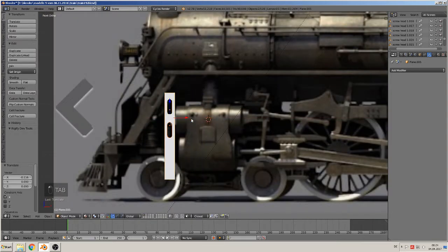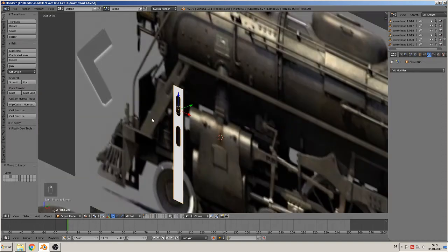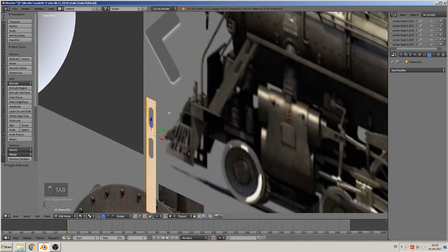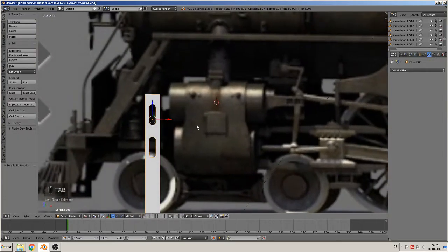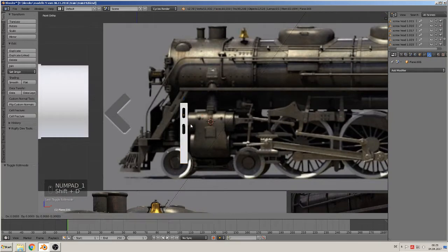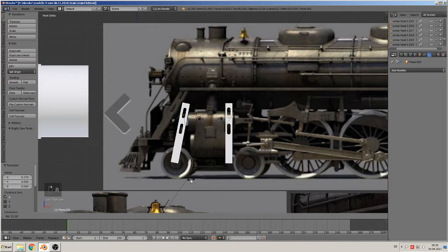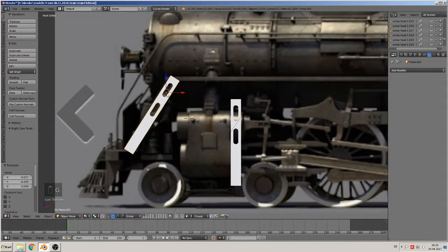Good. We done that. Now we can move that here to the third layer. That here we take and edit mode, extrude in the Y to get a thickness there. We make a copy, Shift D, and now we rotate that to the point that we have there.